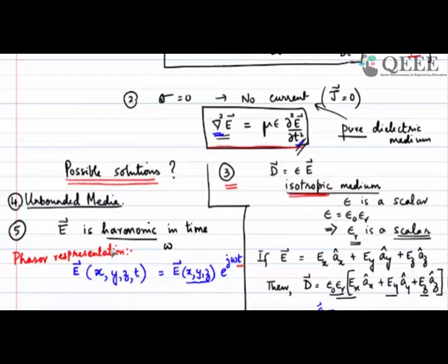When we wanted to calculate the impedance of an inductor or capacitor, when analyzing an AC circuit which has an inductance and capacitance, it was easier to use the time harmonic case because we could use a phasor representation. The power of phasor is that the moment I put it as a phasor, the second derivative in time vanishes. I can write it as a multiplier. I do not have to do a derivative. I will show you how. But that was the power. We have used it in electric circuits, same thing we are going to use here.